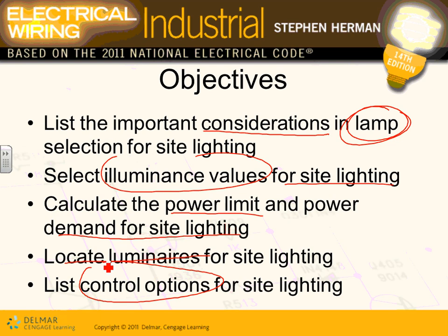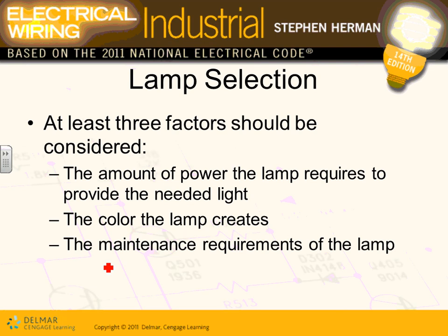So does that make sense, guys? Selecting the light, laying out your light, how do you control the light? Did we use timers? For our project, we selected timers. Power consumption, guys, or energy code, we did ComCheck for this project. So these are the factors that you have to take into consideration. So, Karen, when you are selecting a lamp for the parking lot, we selected the LED for you.